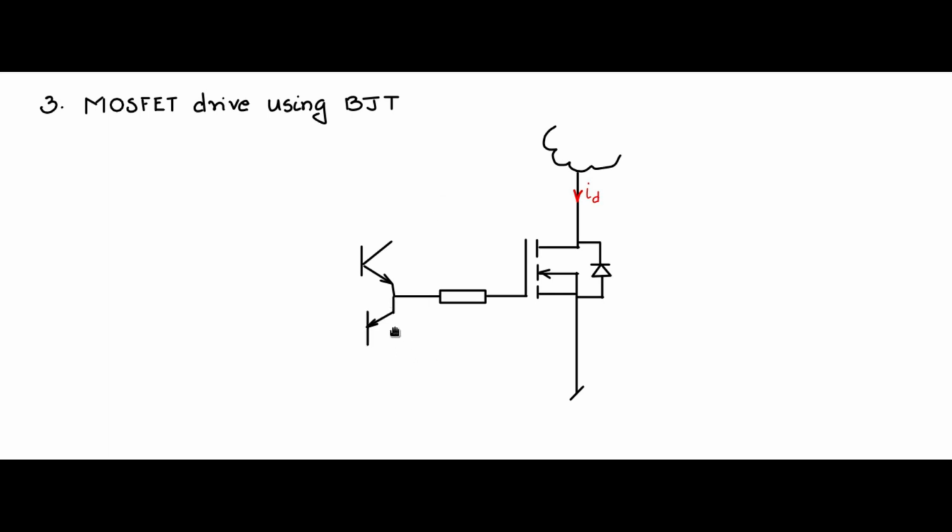So at this point, let me put an NPN PNP combination totem pole directly across VCC, and let me connect both the bases together, and let me drive these bases with a 2 resistor base drive circuit, which we are familiar with, and the drive for this is coming from, let us say, a PNP stage.